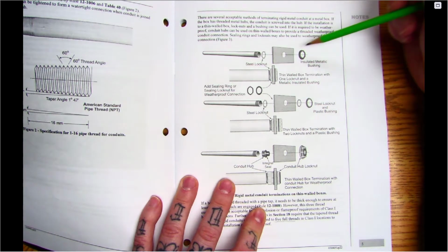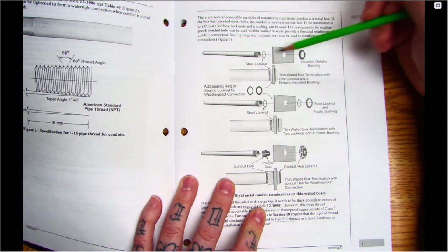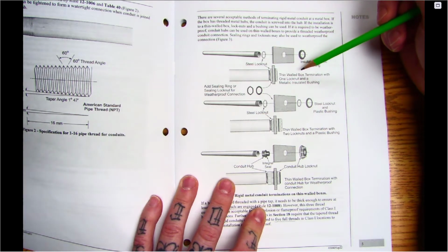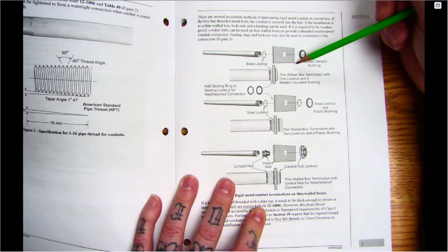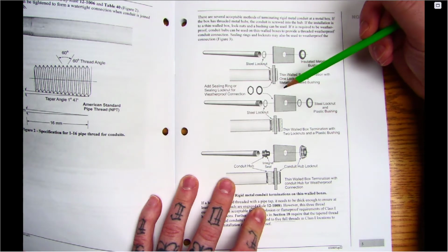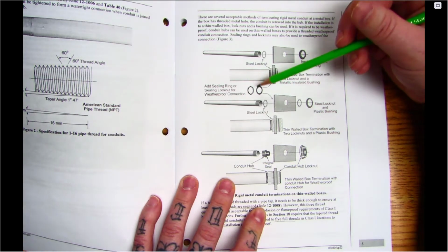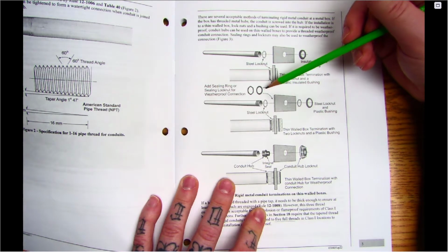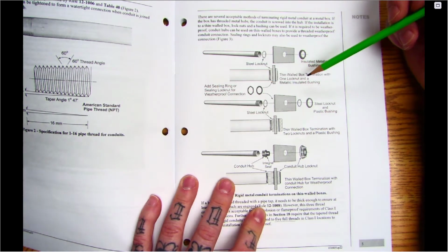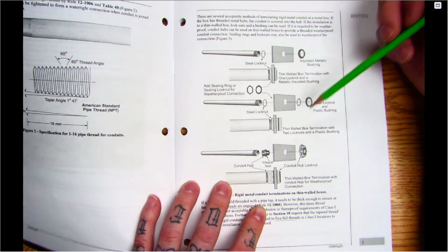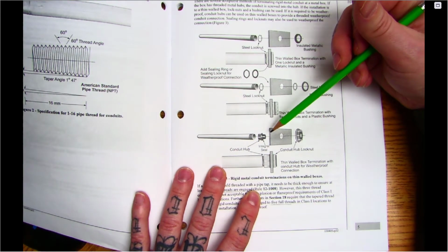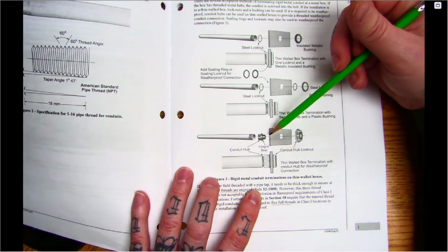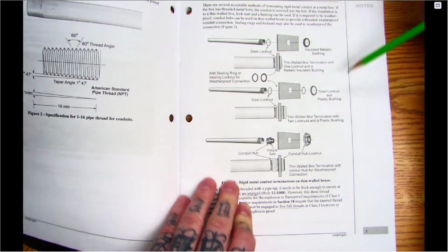this would be a standard lock nut. Okay, and then we got our insulated metal bushing. Again, this is just how we terminate rigid conduit into a box or into a thin-walled box termination. And then whether or not we're in wet locations, so we need a weatherproof, we can get different types of sealing rings or lock nuts that provide that extra protection if we are outside. Then we also have hubs, so if you've worked in the oil field, you probably have seen a Myers hub before. Okay, so we can use those as well too. Just different ways we can terminate it.